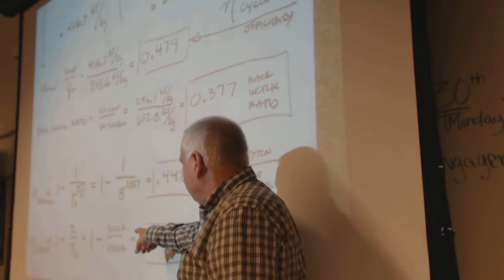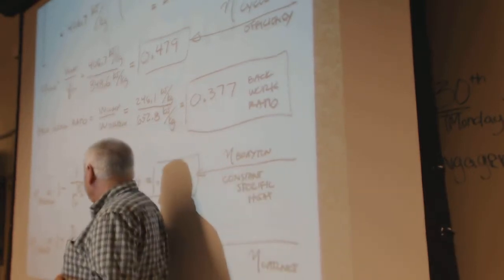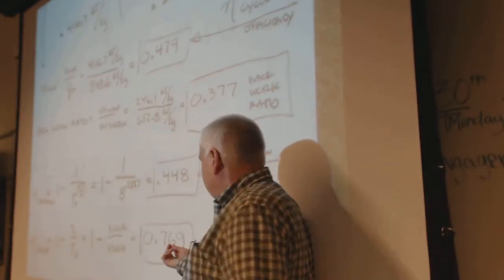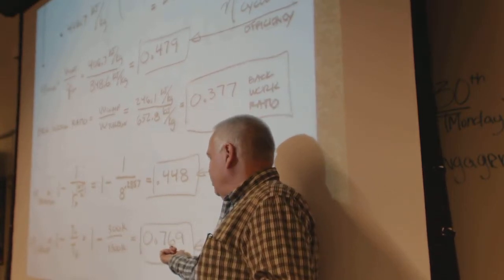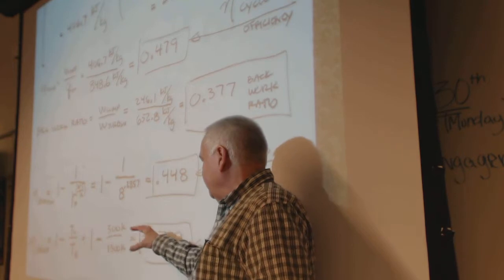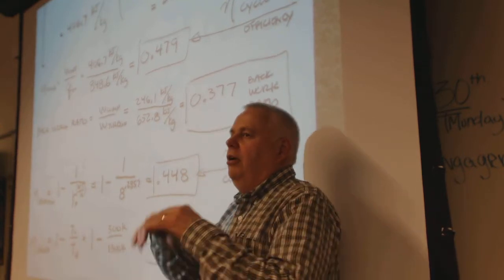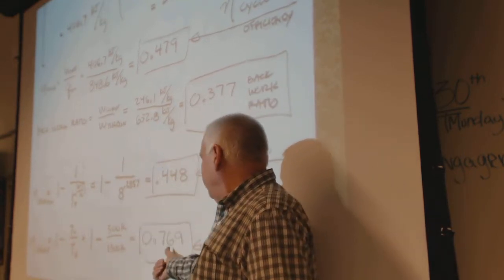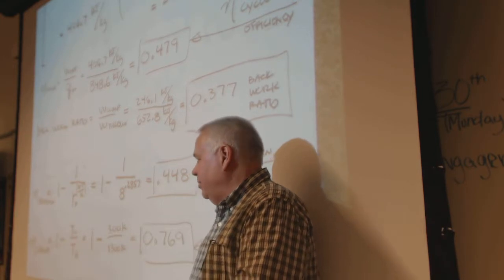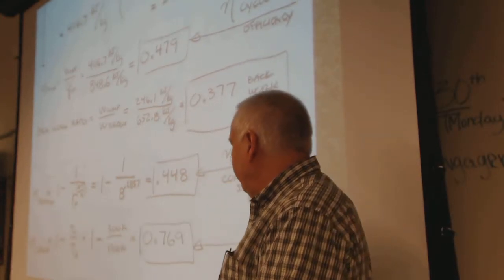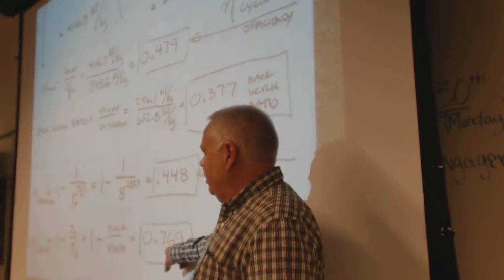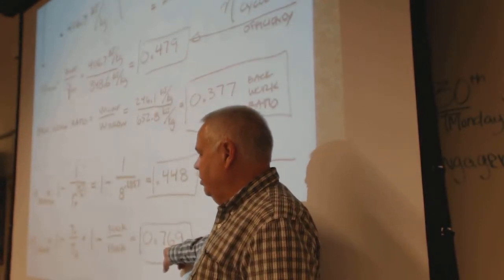If you just look at Carnot cycle efficiency, it says the best, most perfect engine in the world, totally reversible, with all processes, would be limited to about 77% efficiency. If you get an efficiency that's bigger than that, this is a good cross-check.